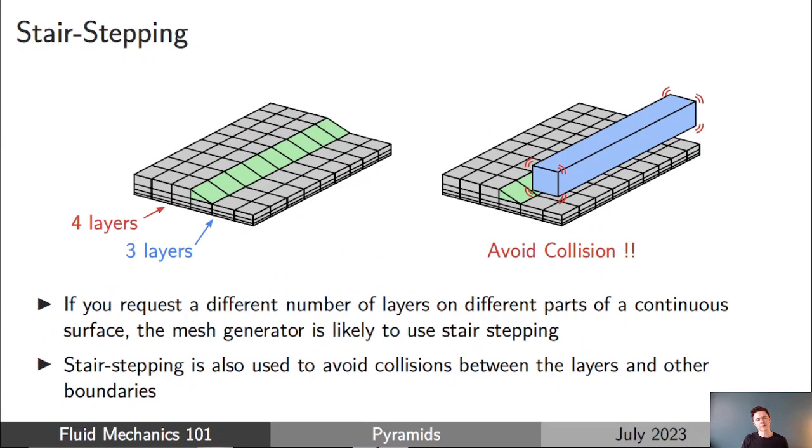And often, if you're using an unstructured mesh generator, of course, you may not request stair-stepping yourself directly. You're not going to tell the mesh generator, I would like you to use stair-stepping. Often you'll click the mesh generator button, and then what will happen is maybe warnings or error messages will come up saying that the mesh generator has used stair-stepping at some locations in the mesh.